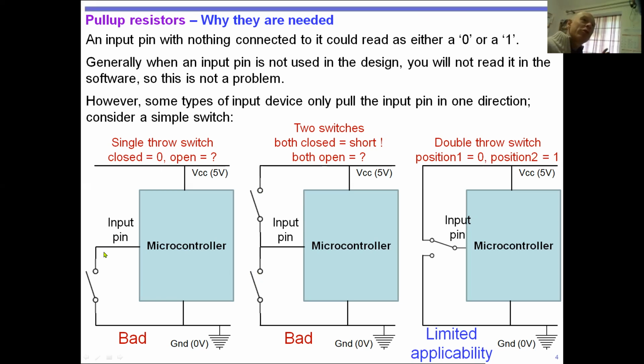We also introduce a new danger, right? If we have them both open, we have the same problem. That's not a new danger, that's the same danger, but here's a new danger. If we connect both of them together, we short circuit the power supply and the microcontroller will reset itself. So we've got even more danger now. We're randomly resetting the microcontroller, because when you release them again, it will reboot the microcontroller.